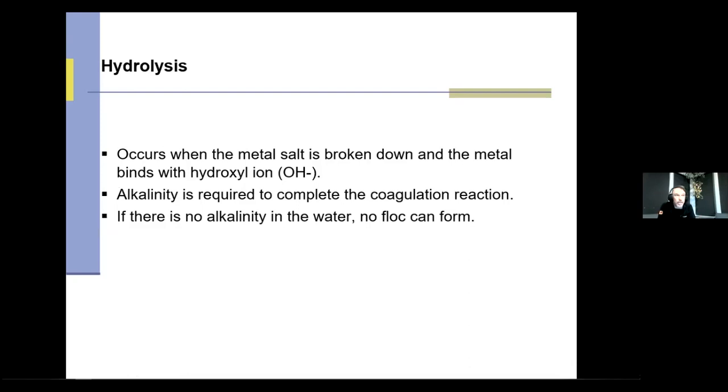Alkalinity is required to complete the coagulation reaction. I can't stress that enough. If there's no alkalinity in the water, no flock can form. And you can put as much coagulant as you want in the water. If you run out of alkalinity, it isn't going to work.